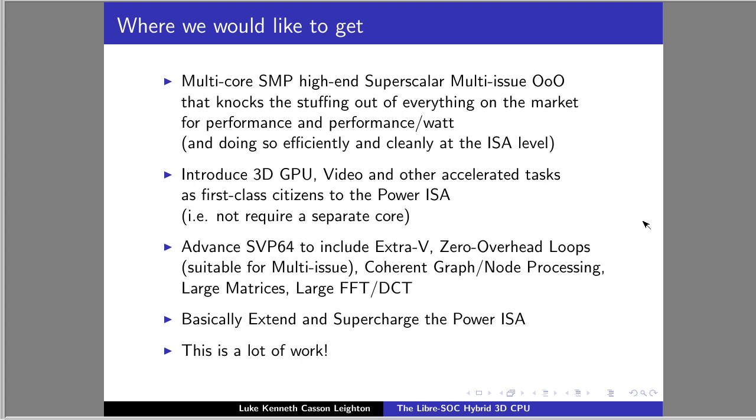I don't know if you've ever looked at the way that GPUs operate, but because you have a separate core, to keep it occupied they have tens of thousands of queues. You have inter-process communication using shared memory over PCI Express, or in the case of an embedded GPU, you have a shared memory area, and it's memory-mapped I/O. The memory space of the GPU is mapped with the CPU.